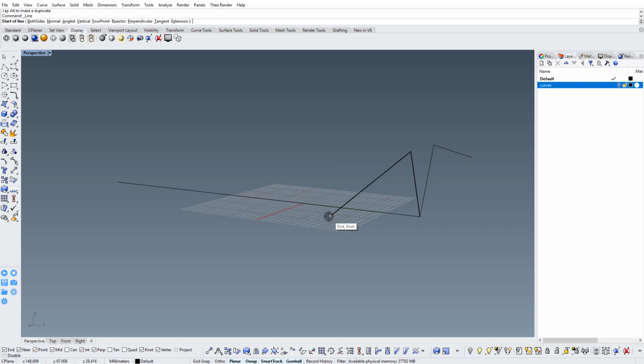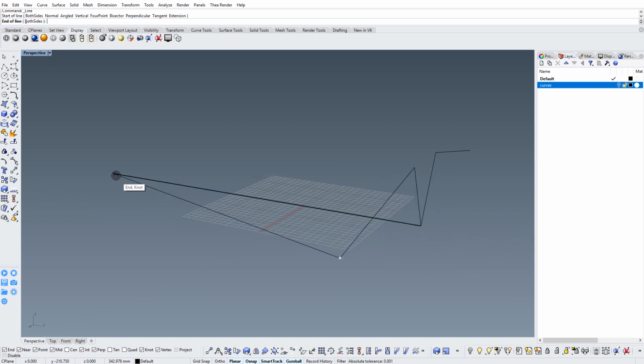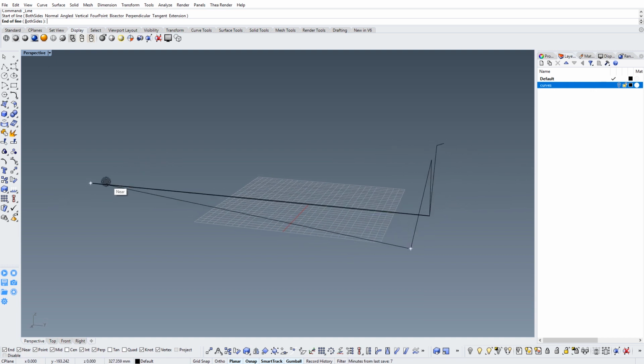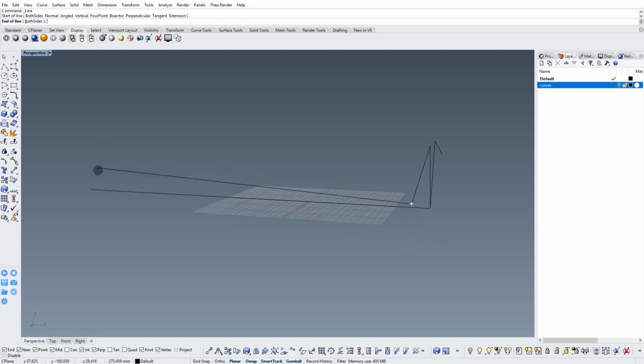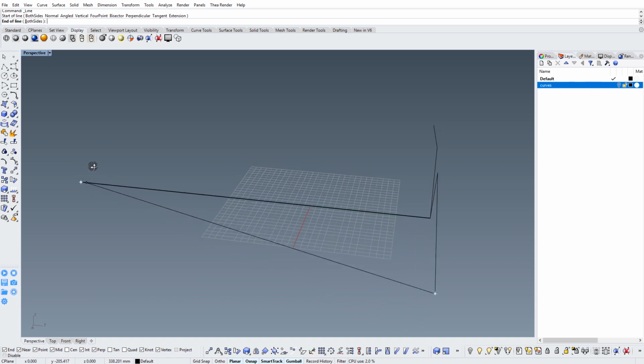Select, let's say this wingtip. And if I go to this point, I go also down to this point. But what I want here is to be in the same axis, in the z-axis here, in the height, but to be on this spot from the top view.